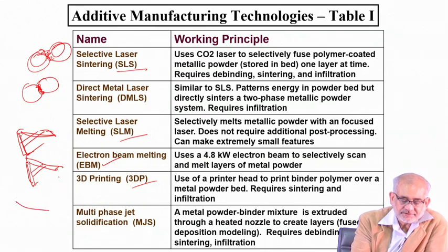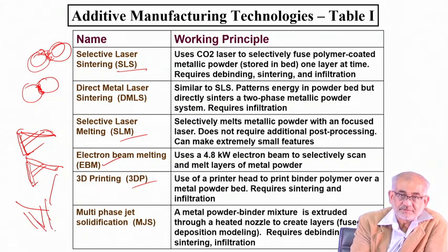Usually the powder feed and the laser can be different, coming from different directions, but in principle, or in reality even, it's also possible that you have a laser beam coming through a particular nozzle, and you have a concentric feeder or hopper around it, which can feed one single or multiple powders.